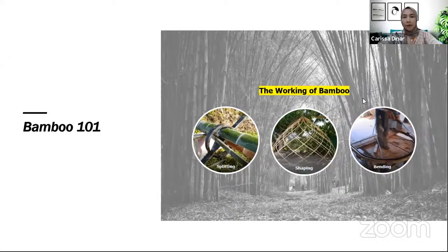All right, next, the work of bamboo is used as per the desired need and length. First, splitting. The bamboo cane is split in quarters and then driven apart by a wedge or a knife. By means of splitting, you will get halved canes, strips, and battens. To get planks, all the nodes are smashed and the wall of the pole is split over its entire length and forced open until the wall of the pole lies flat.